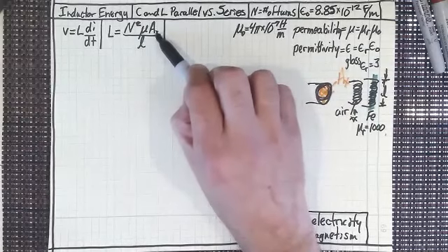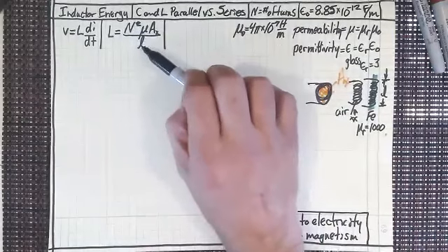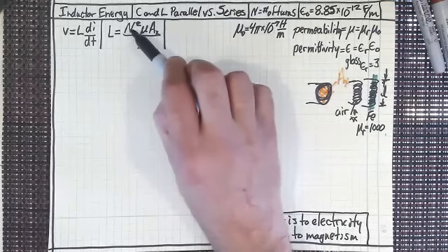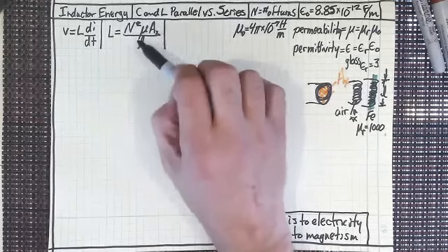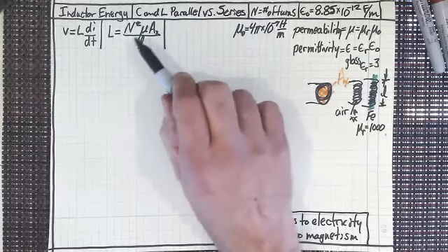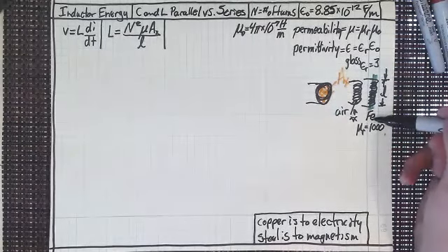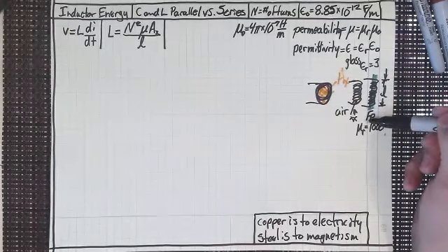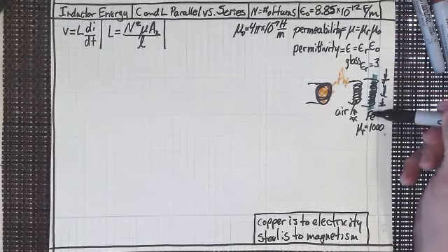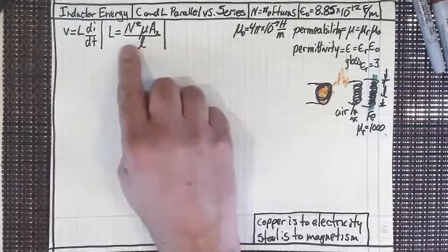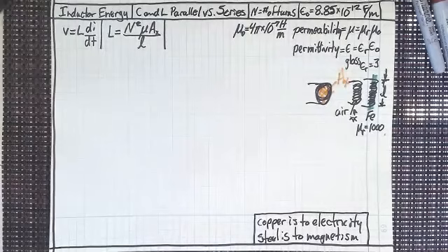They actually did get a toilet roll, and they knew what the cross-sectional area of the toilet roll was, and they knew what the length of the thing was. They could vary that a little bit. And then they just had the turns, and they used air core. They could even make it into a variable inductor by sliding this steel rod in and out. That's how you tune that inductor, to get different frequency radio stations. Anyway, I thought I'd bring that up. That's not something we're really going to be looking at here, except to understand how an inductor is put together.